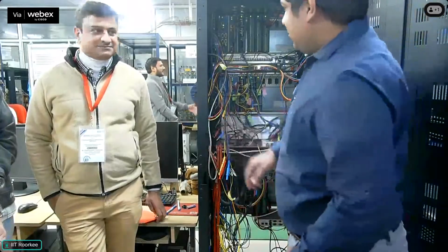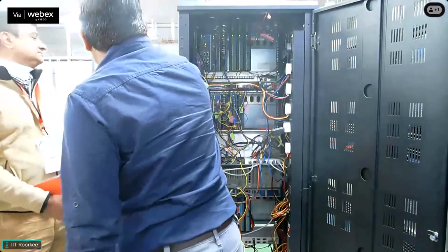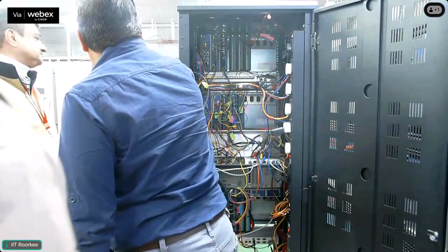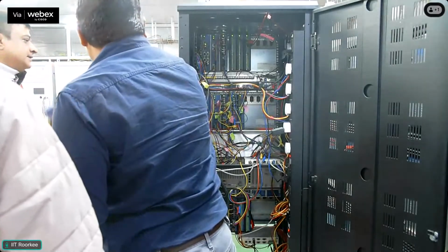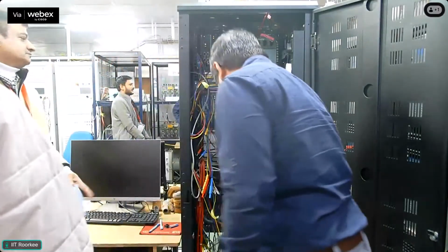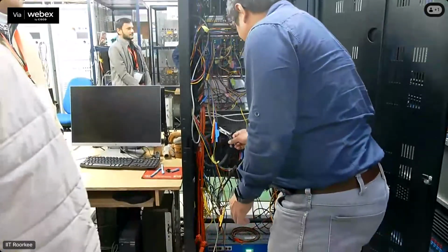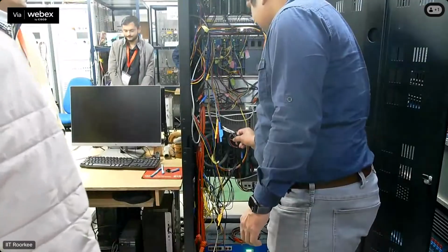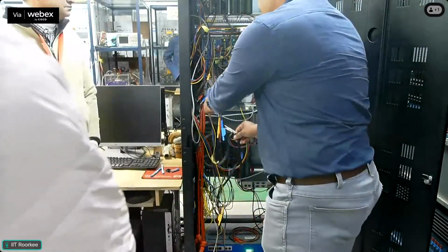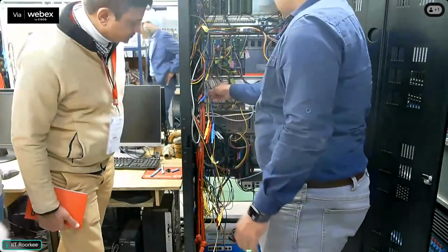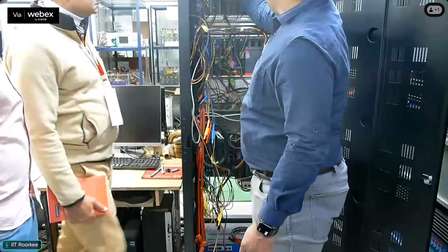So in this, if you can see, we have come from RTDS through the GTO card to this amplifier. Then through this amplifier, if you see this cable coming out, it has these 3 voltages and neutral, and this is 3 currents and neutral. So from the amplifier, we give it here, and these wires are going to the CT module of the PMU.